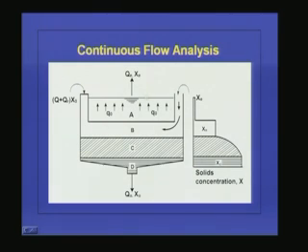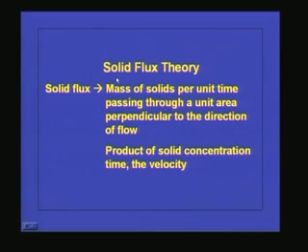So, two forces are acting on the sludge. Because of the withdrawal of the sludge, there will be some velocity with which the sludge will be coming down, and another is the weight of the particle, or the gravity force, because of which some thickening will take place. If you want to take both into account, we can use the flux theory for the design of the secondary sedimentation tank. So, what does the solid flux theory say? Before going into the solid flux theory, we will discuss what solid flux is.